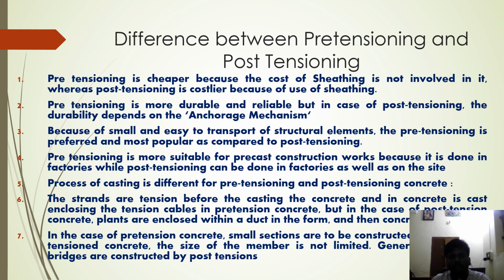Because of the small and easily transported structural elements, pre-tensioning is preferred and most proper as compared to post-tensioning. Pre-tensioning is more suitable for precast construction works because it is done in factories, while post-tensioning can be done in factories as well as on the site.